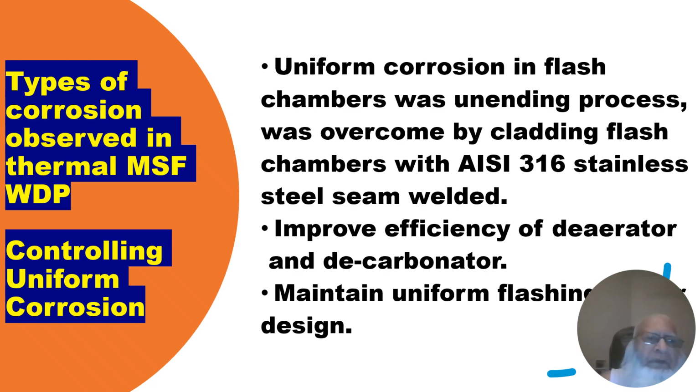The continuation of the same slide is types of corrosion observed in thermal MSF WDP, controlling uniform corrosion in these water desalination plants. Uniform corrosion in flash chambers was an unending process, was overcome by cladding flash chambers with AISI 316 stainless steel, seam welded.